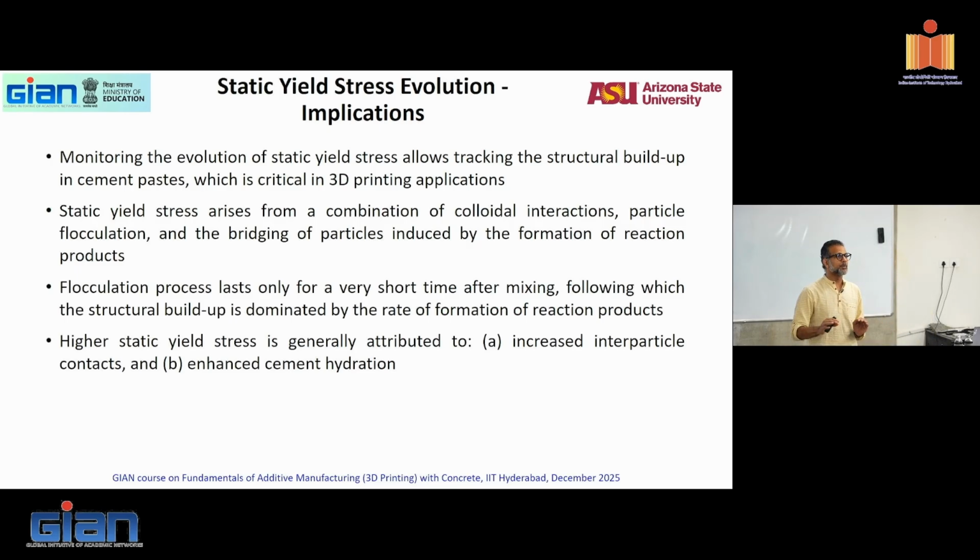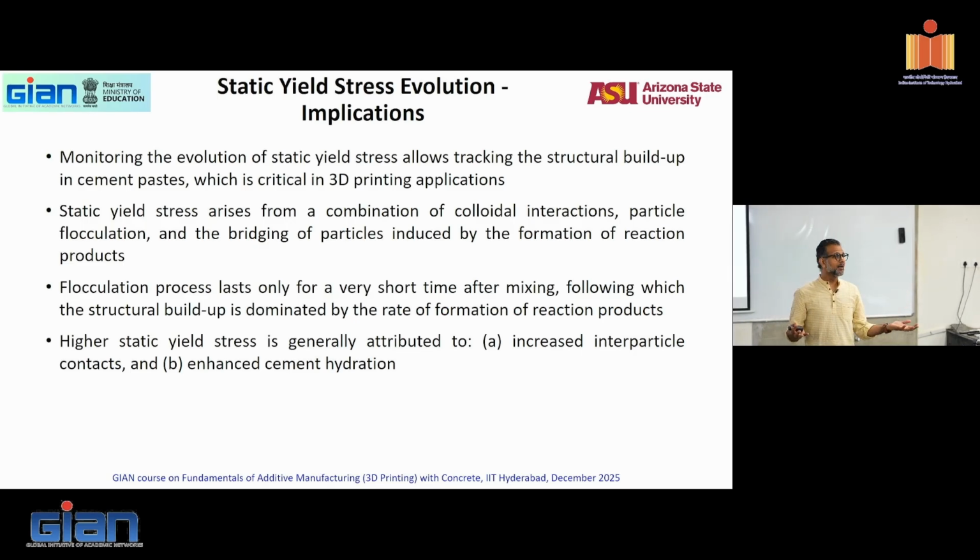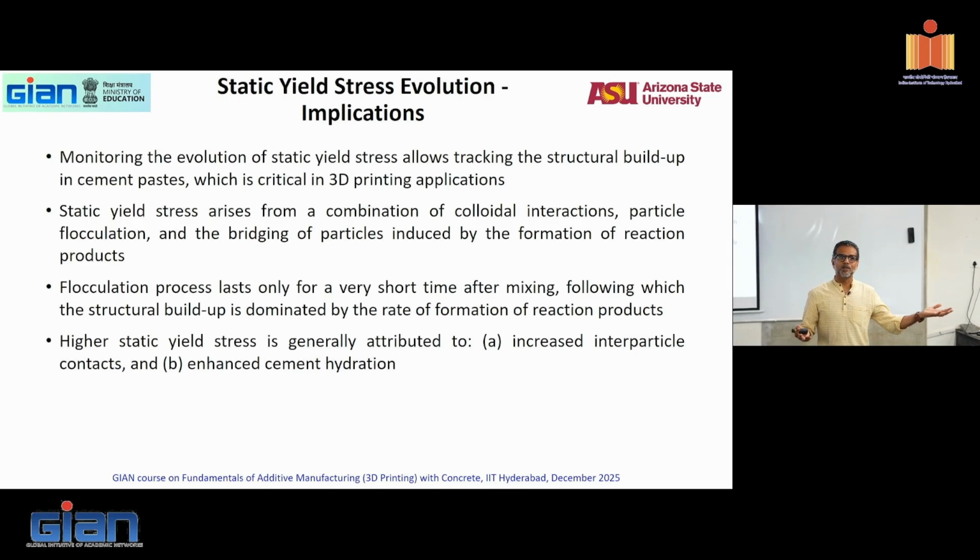So now we are doing it with time. Now there is a question: how much time will my rheometer allow me to measure this? Right? It depends on the capacity, the torque limit of your rheometer. So if you have a rheometer that has a lower torque limit, you might say, you know what, at 15 minutes, all my calculations are ended. After 15 minutes, don't ask me what it is in my printing. You go find out on your own, extrapolate.